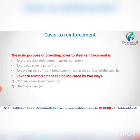Next, cover to reinforcement. Why use cover? The main purpose of providing cover to steel reinforcement is, first point, to protect the reinforcement against corrosion. Second point, to provide cover against fire. Third, to develop sufficient bond strength along the surface of the steel bar.